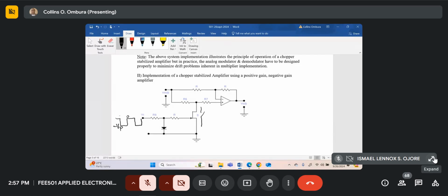In the last class, I gave you some data of some chopper FETs, and we saw the voltage required to switch it off ranged from maybe minus 0.3 volts to maybe minus 4 volts. They vary depending on the manufacturer. So just make sure your control voltage opens the switch and also closes the switch.